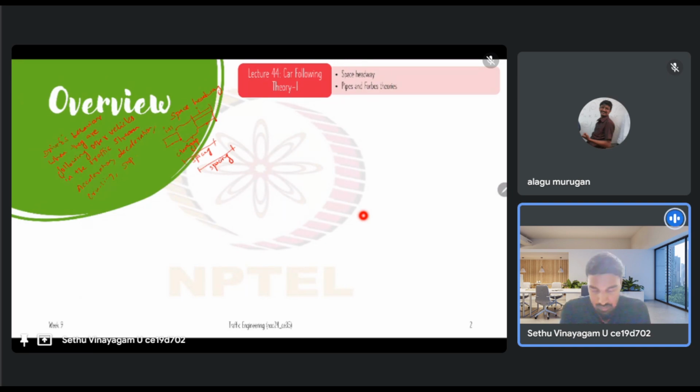So why is this important? It is because this influences the decision, right? As we can imagine, if the vehicles are too close, the space headway will be smaller. In that case, the follower vehicle, which is I plus one, will be very careful to changes in the speed of vehicle I, right?